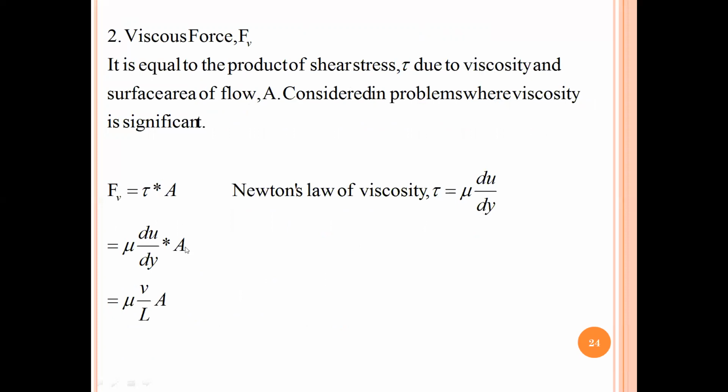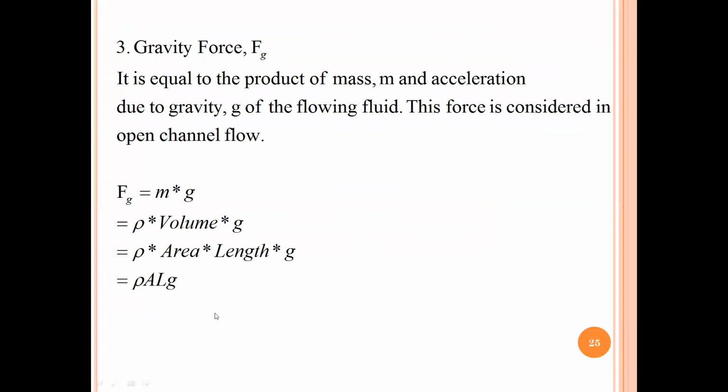mu du by dy into A. Your du is your change in velocity, so I can replace it with velocity. Dy is a length, I'm writing in terms of L. So mu V by L into A is your viscous force.